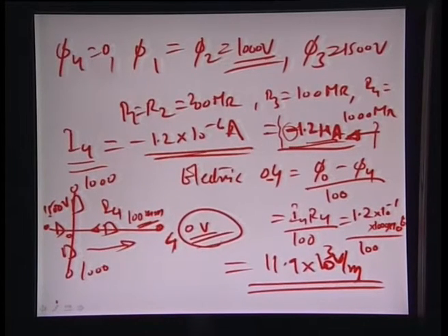Let us calculate the velocity of flow in the particular microchannel based on all these assumptions. The first thing that I would like to see here is to determine the mobility of the ions per unit electric field. If you remember the equations that we derived on electroosmotic flow, the mobility is also the velocity of the ion in a unit electric field. So here the mobility can be defined as mu 0 equals epsilon 0 epsilon zeta by eta.